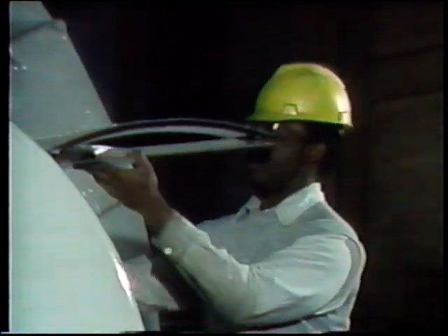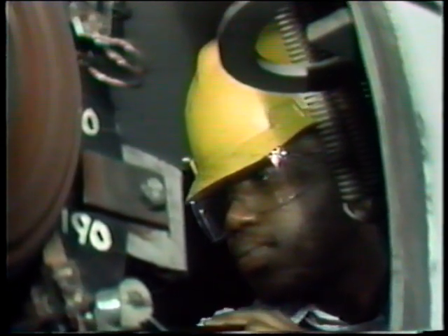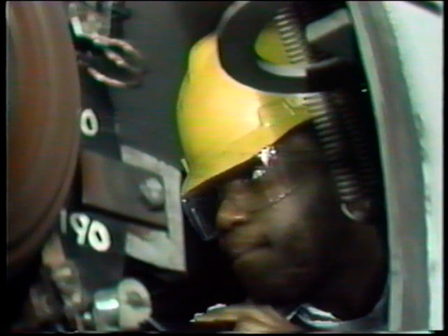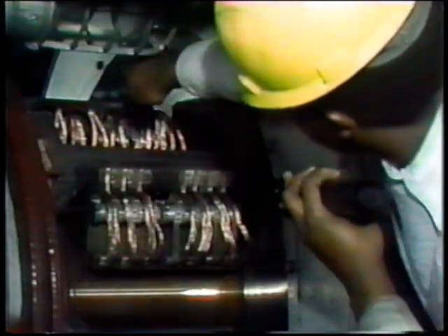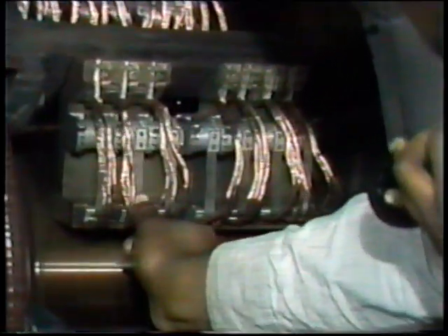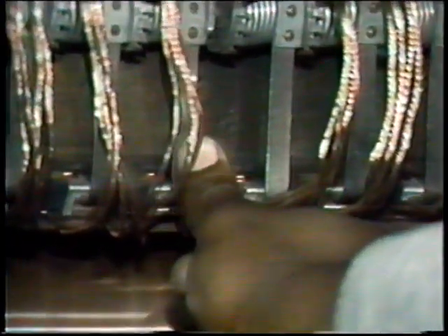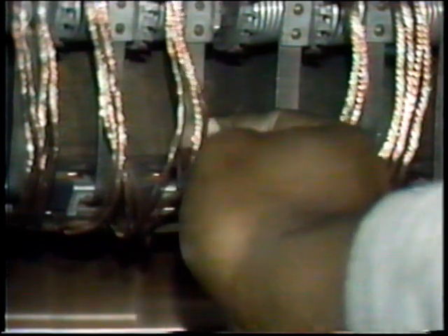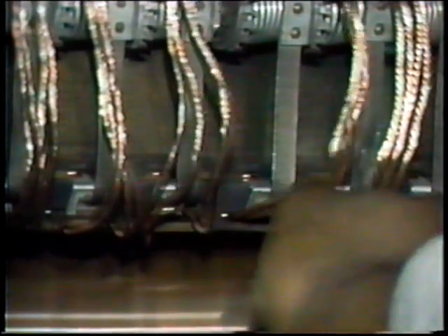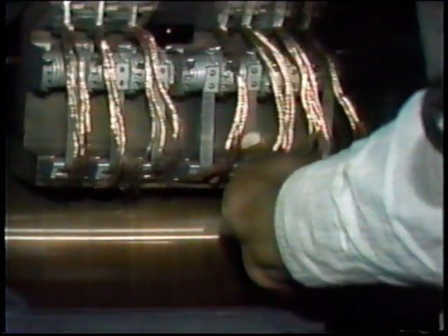Next, he inspects the main exciter brushes in a similar manner. Again, he looks for good contact between the brushes and the commutator and for anything unusual. There are more brushes on the main exciter than on the pilot exciter, but the inspection procedure is basically the same. Here, the electricians found a problem, a short brush. It would wear out before the next time he checked it, so he'll replace that brush later, after checking the other brushes.